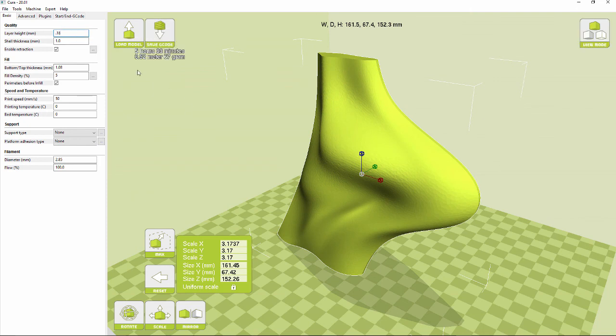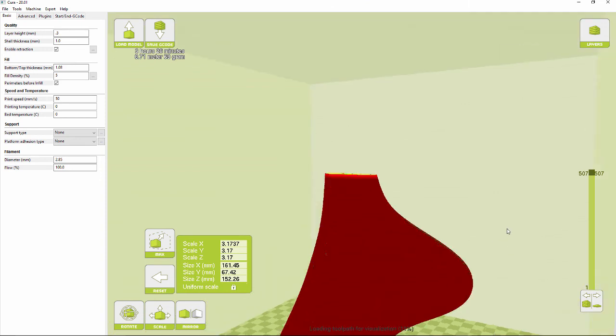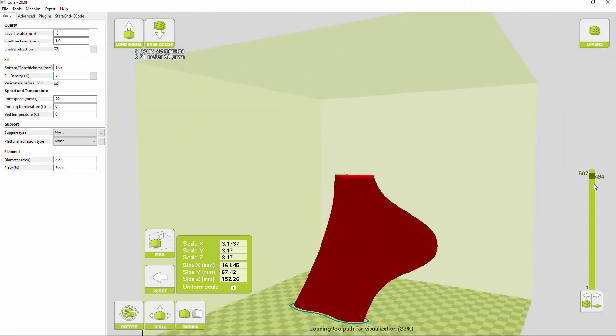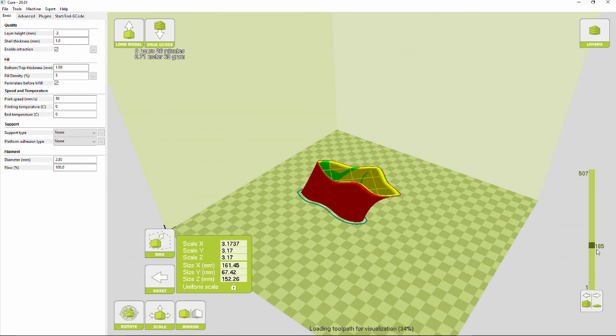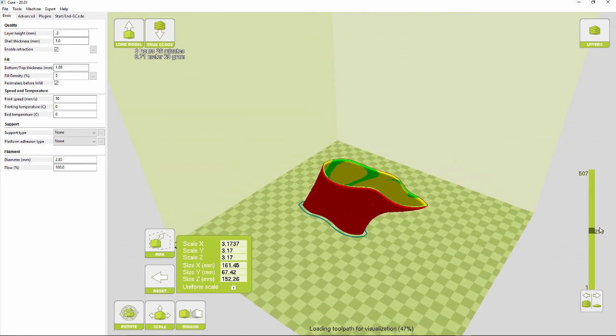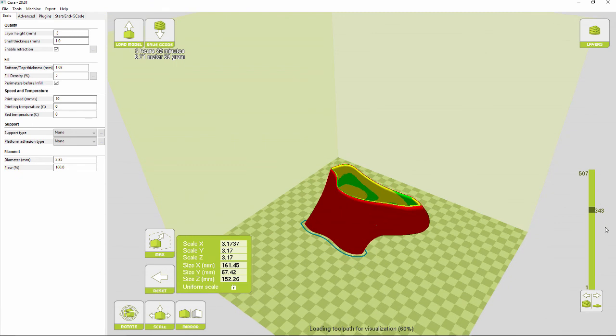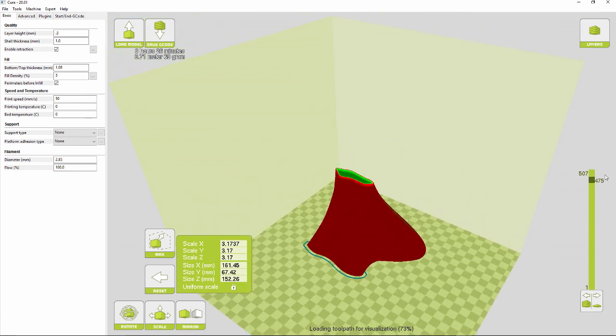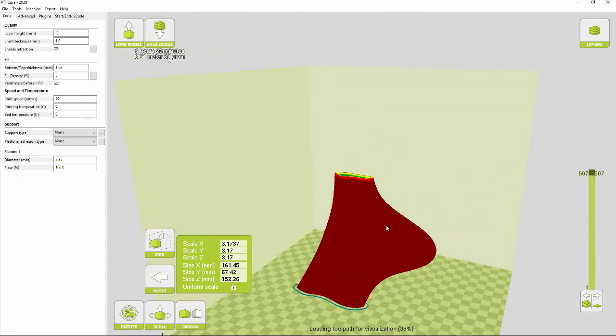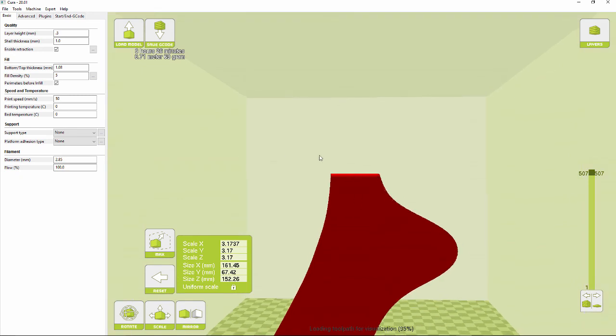For something final, maybe we need that 5.5 hours. That's not bad, but the quality difference, setting that to 0.3, and that's how many layers I have, will be perfectly fine for an architectural model. If I switch my view mode to layers, you can see a little bit more information about how that's going to print, just like that. You can see a little bit of where that infill is going to happen, and how that will give me a little more structural integrity in terms of that form. Maybe it's worth that 26 extra minutes.